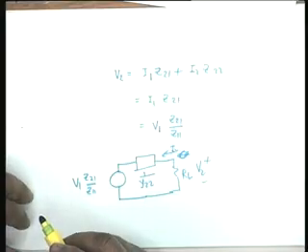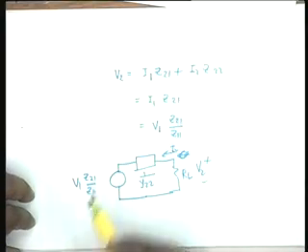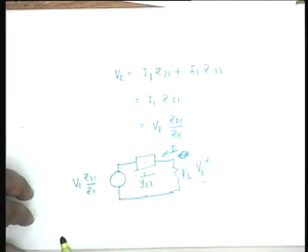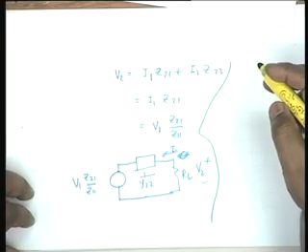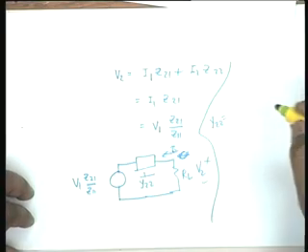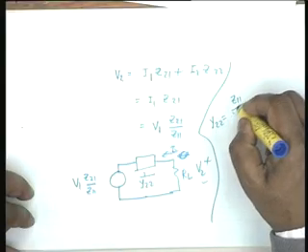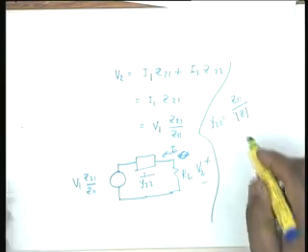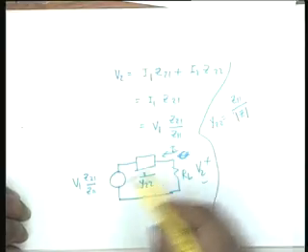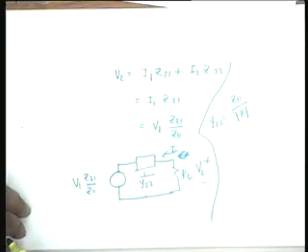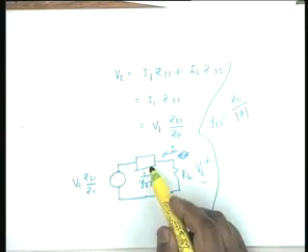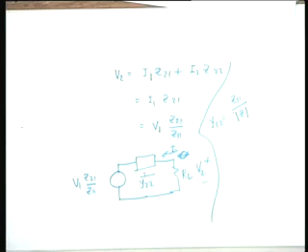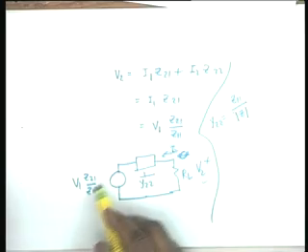The only problem is that instead of all Z parameters there has occurred Y parameters, and we shall show later, because the Y matrix is the inverse of the Z matrix, Y22 shall be equal to Z11 divided by determinant Z, and that's how Z11, determinant Z, Z21 and Z11 will come in the calculation. Now it's a one loop network, nothing to it, V2 by V1 shall be simply potential division between these two. Okay, the input impedance, oh, that's a problem. Input impedance cannot be calculated from here.